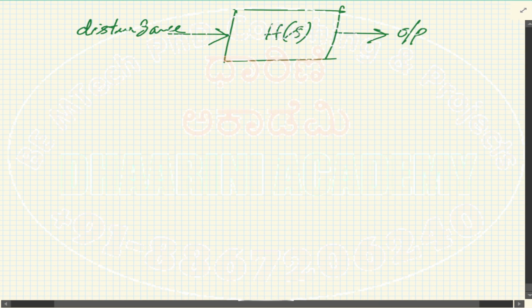But exactly by what amount, what will be the exact value of the load of the whole city today? We cannot guess, but the shape can be guessed. It's maximum, then it reduces. You can come to a close approximation by looking at yesterday's and the day before yesterday's data, but not the exact one. So you see that is what is considered as a disturbance signal: you can guess the shape.